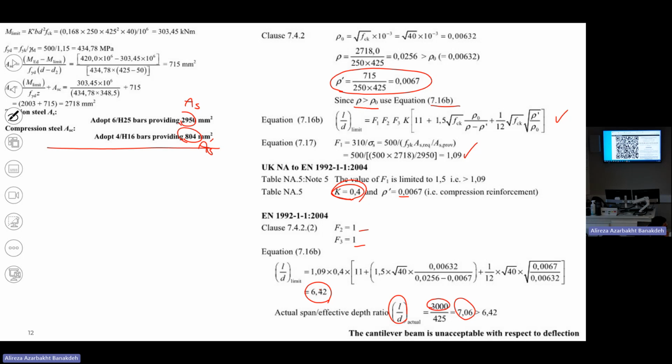Usually. I don't say you cannot design a balcony of 3 meters with pre-tension or post-tension, but if you design a balcony for 3 meters here, you cannot make it fine. If you increase H, you will come up with the fact that you need a section like this, and you cannot construct that section.